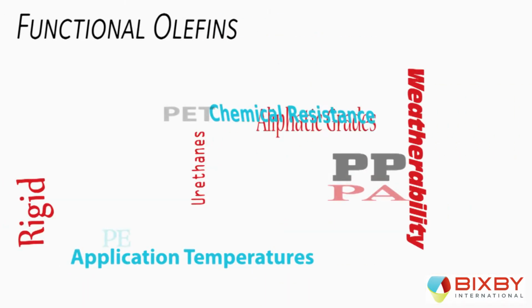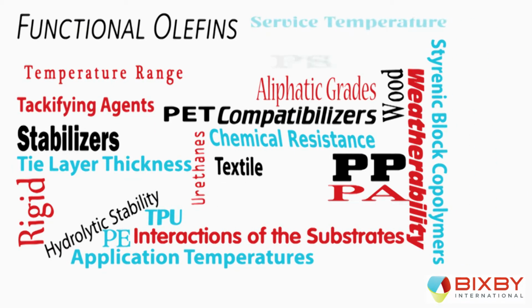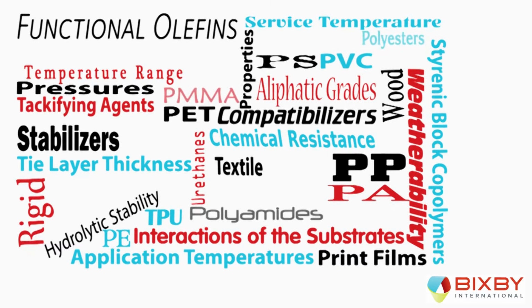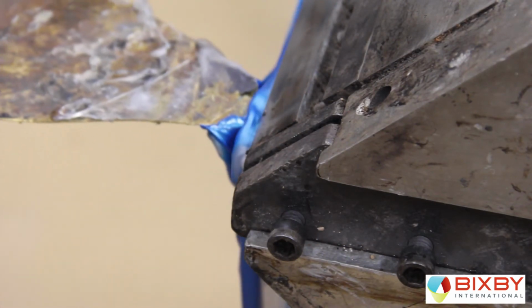Functional material interface layer chemistries and the proper tie layer for those play a key role in achieving optimum bond strength. It often comes down to hot melt chemistries, which is why it's crucial to choose the correct materials. However, this phase of the process, like much of everything that has preceded it, is not cut and dry. There's many hot melt chemistries available from many different vendors. But there's also another alternative when you're trying to optimize your tie layer in a laminate construction. Bixby not only knows and works daily with a myriad of commercial hot melt chemistries, it also formulates its own hot melts for custom applications, by putting color, conductivity, or UV blockers into the tie layer to give additional functionality to the laminate.